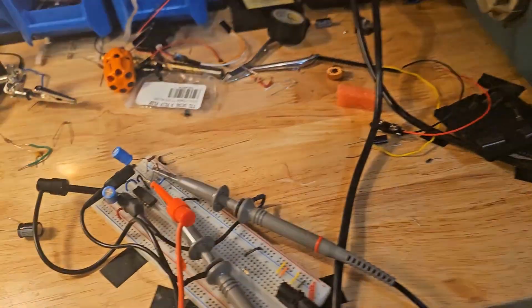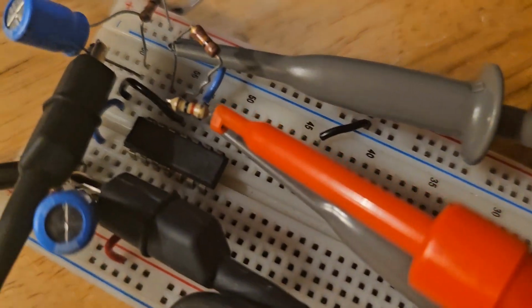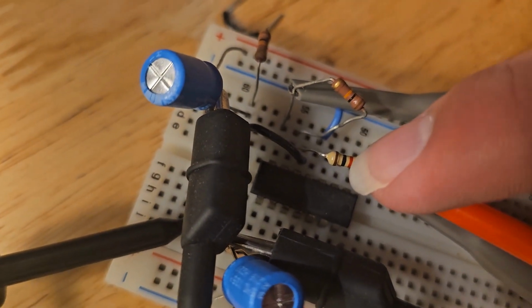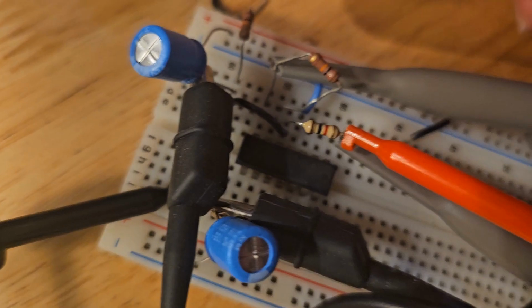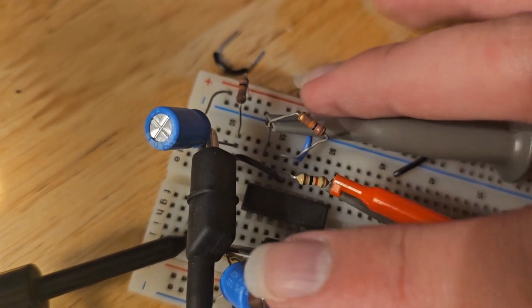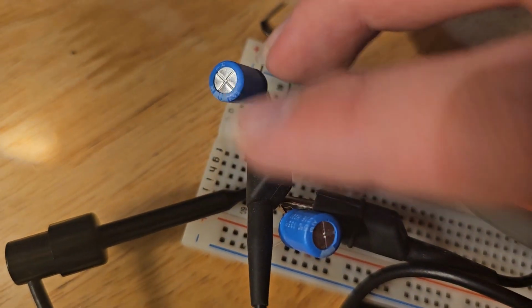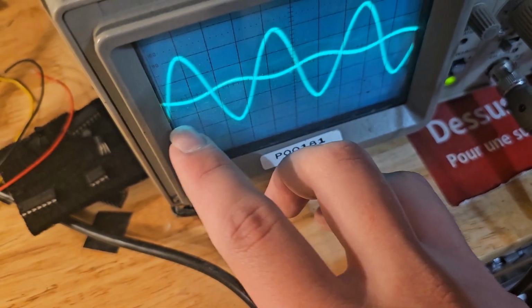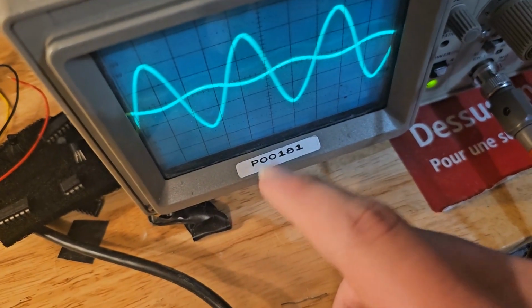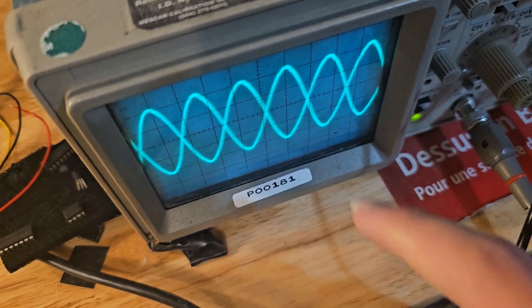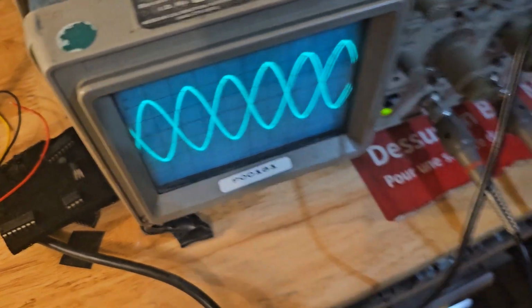Alright, so here's the actual circuit. It's a little bit hidden up, but as you can see, we're using a TL074 quad operational amplifier. There's the 1 kiloohm resistor, 10 kiloohm resistor, and these are the resistors and capacitors creating the voltage divider. So that's what we have. As you can see, this creates an output signal that is 10 times larger than the input, and if we amplify the input a little, you can also see that they are exactly out of phase. So there we go, that means that this worked.